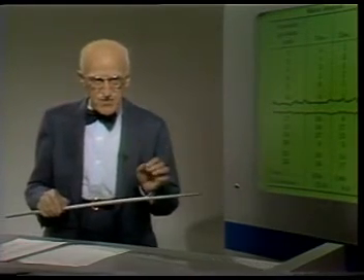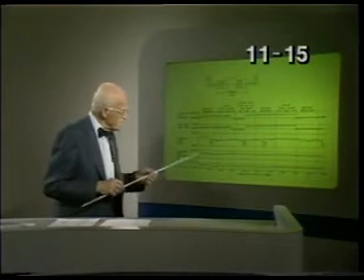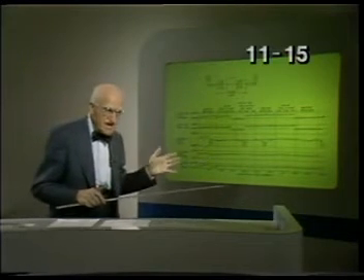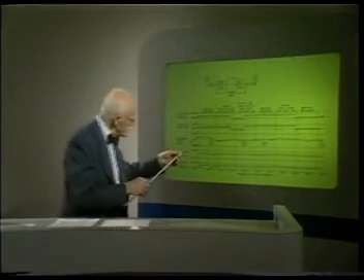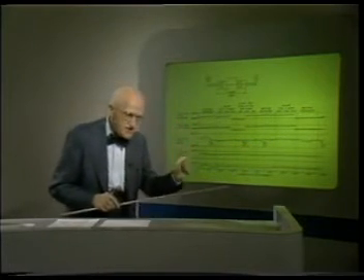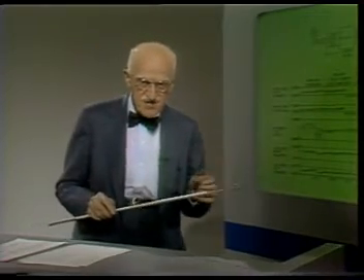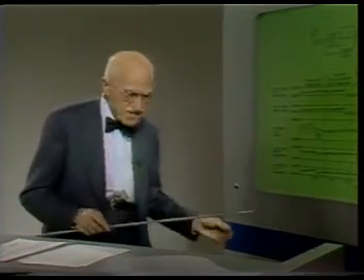Our earliest example was a study of several hours of production of shafts for the watches. That study showed a time-to-time variation. The diameters grew progressively larger due to wear of the cutting tools. We also saw an example of cyclical change in the carpet yarns.